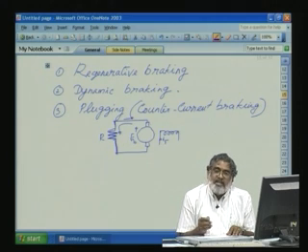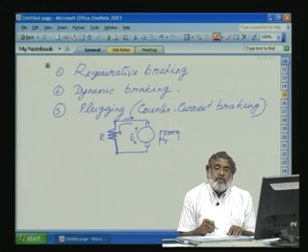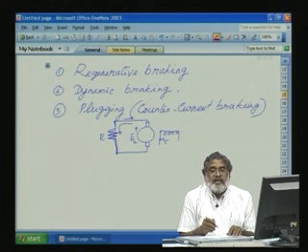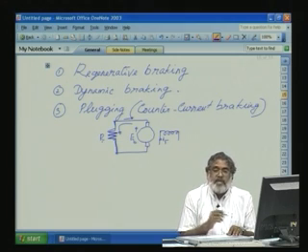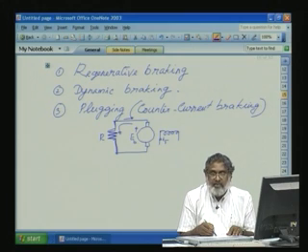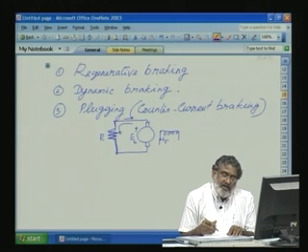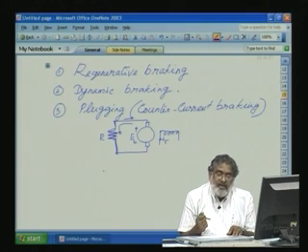For a machine, there is always a rated current, because the current value depends on the heat generation and the thermal management of the system. So, we have to limit the current flow in and out of the machine within that range. We will choose R such that for the maximum EB at maximum speed, the current will not go more than the rated current. Once R is connected here, the system will slowly come to 0.